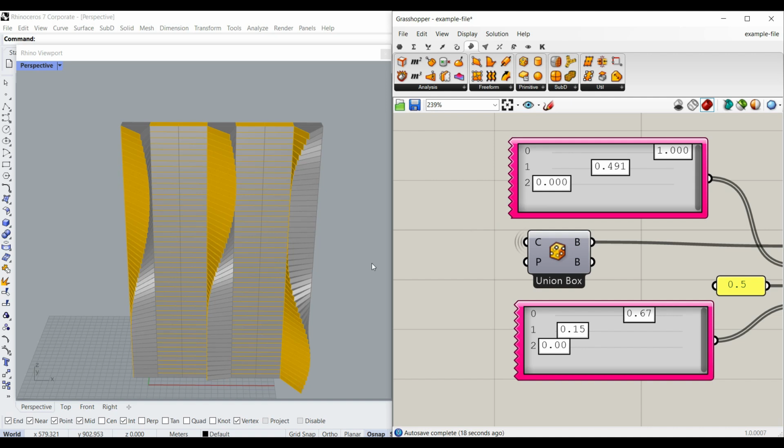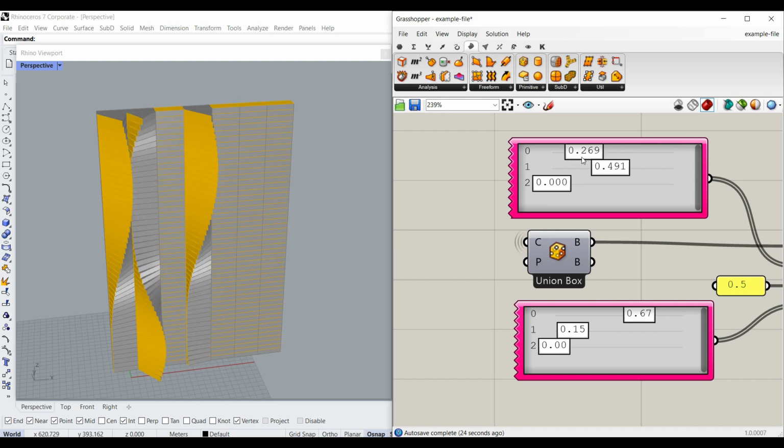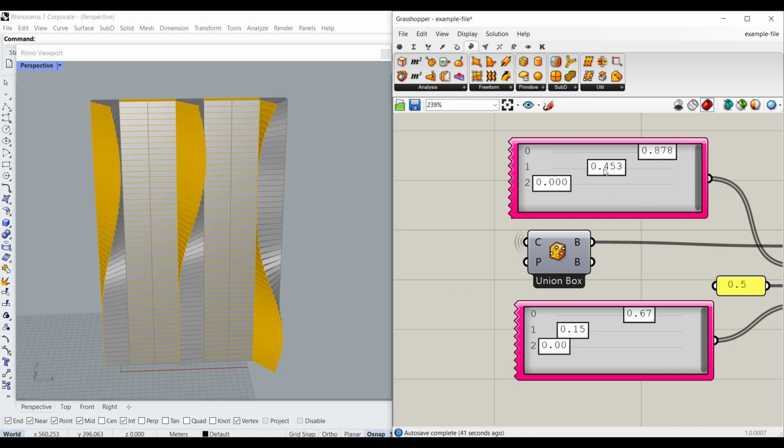We're also going to define the location of the rotation with two parameters. One is the location of the column we want to rotate. So for example, you can see that I can change the location. If I give it 4 sliders, it's going to be 4 columns. And another slider is going to control the center for the graph mapper.